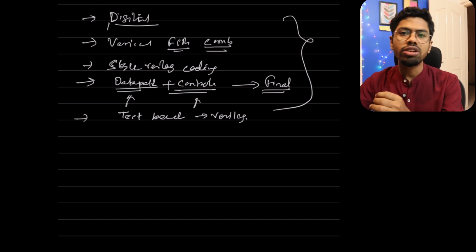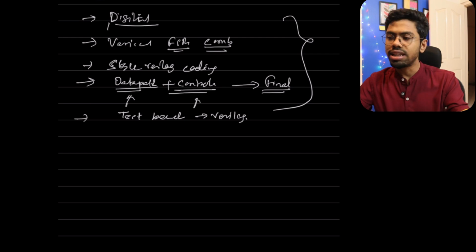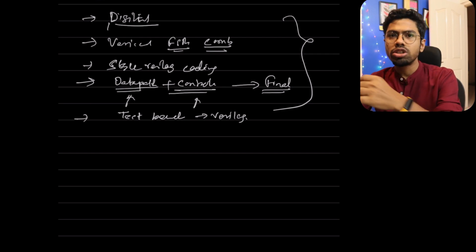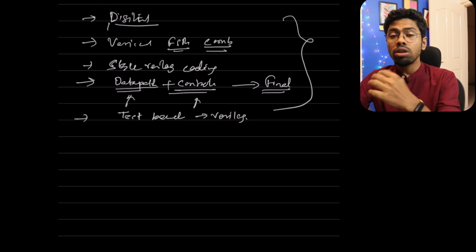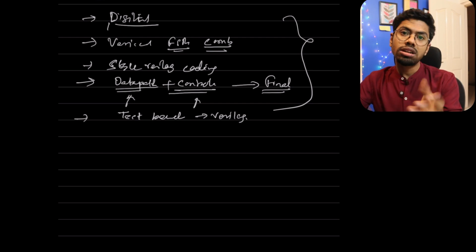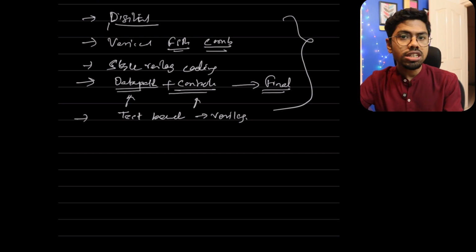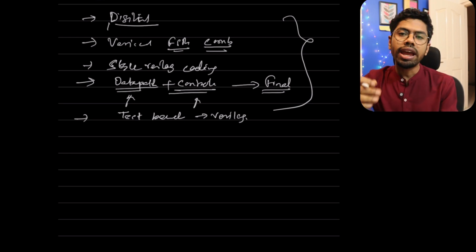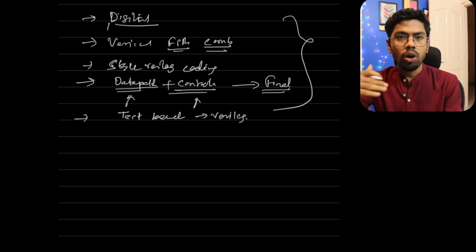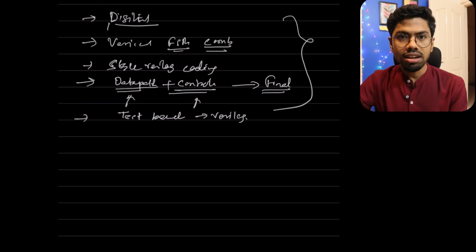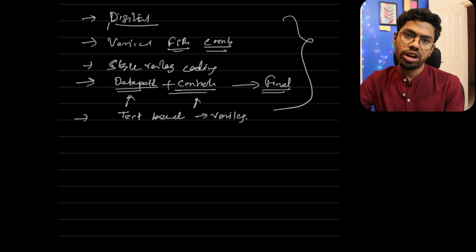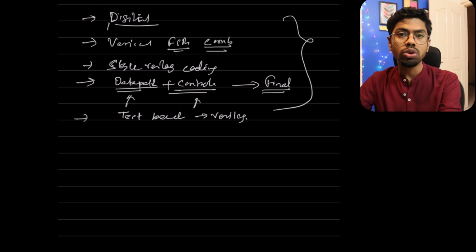So you need to design your ALU. We will discuss in detail. You need to design your logical unit, right? You also need to design the instruction registers, and also the decoder part. Why is this required? Because anytime I say add A, B, our computer is never going to understand what add means, or what A plus B means, or what steps are required. So we need to have some decoder there.